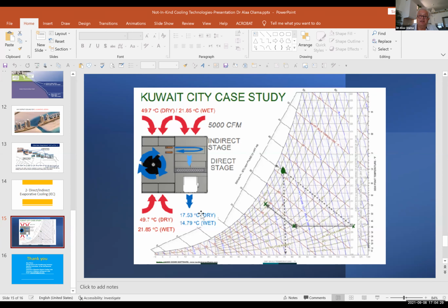Increases efficiency, because the system uses evaporation, direct and indirect evaporation, to get you the efficiency that you are looking for. So what we are recommending now is to use a direct, indirect evaporative cooling system tied to the sort of system where you get your chilled water originally from one of the 17 technologies that I talked about at the very beginning. By doing those two combinations, we can reduce cross-contamination to a great deal, and also increase the efficiency of the system.